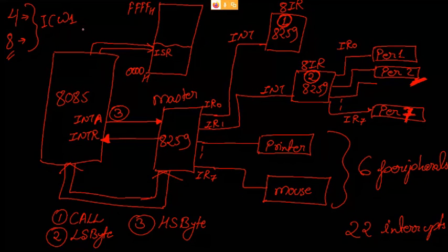And for the rest of the bits, we need to provide 8 bits, right? Because ICWs are 8 bits. So in case of 4-byte address, we are using 3 bits in the ICW1 to specify the address. In the 8-byte case, we are using 2 bits, so the rest of the 6 bits are provided by the 8259. And in case of 4, if you are using 3 bits, then the rest of the 5 bits are provided by the 8259. We discussed all these things.